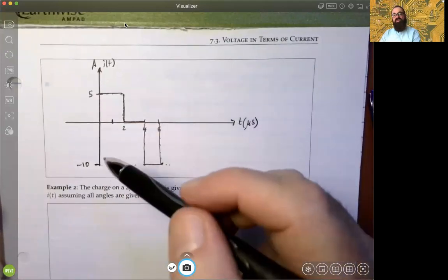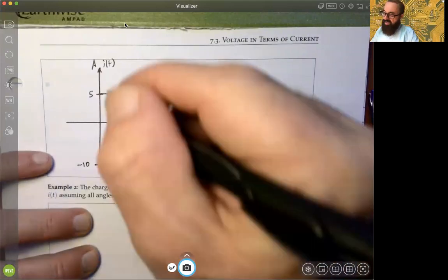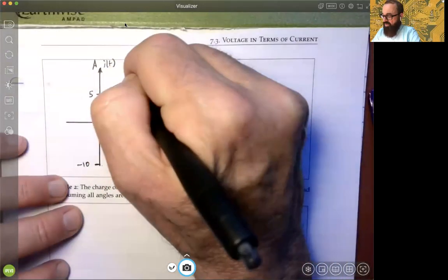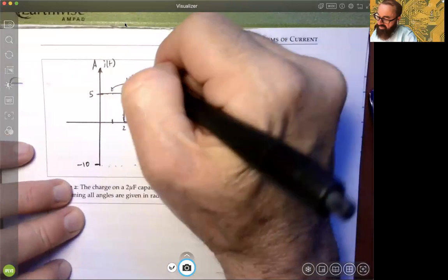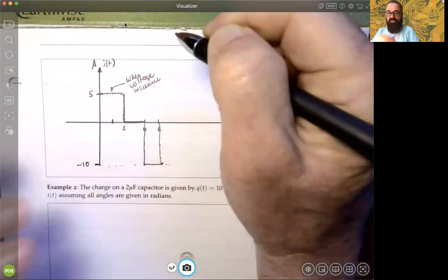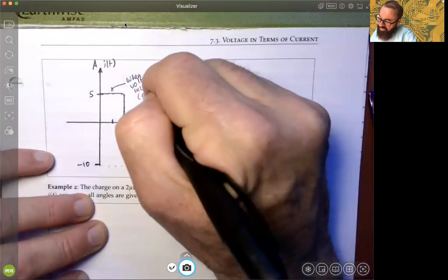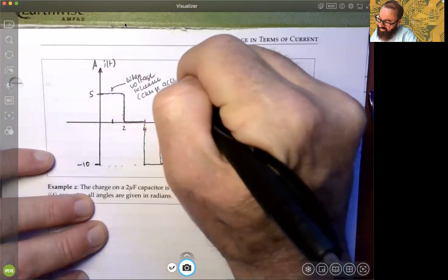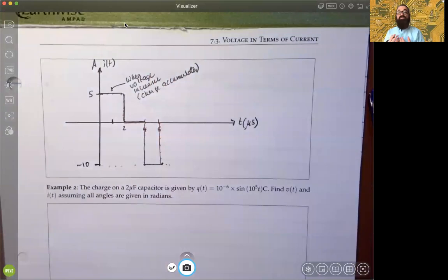What's interesting is that the current graph shows you exactly what the capacitance is doing in terms of charge. You're getting current when the voltage increases. That was a positive slope on the voltage curve. So when the voltage increases, your charge accumulates. Keep in mind the capacitor is storing energy, so the electric field is building up more charge. You're accumulating, provided you keep changing the voltage in a positive way.